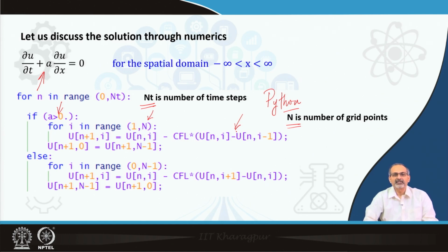I had briefly mentioned about this in an earlier lecture, that how to discretize a linear advection equation using upwind scheme. So, an upwind discretization has been applied over here. We had also talked about the CFL number, because that has to do with the numerical stability of the solution. And then the n over here basically indicates the time step at which you are performing the calculation, and the I is basically the spatial location.